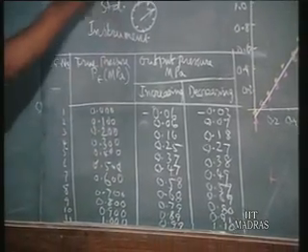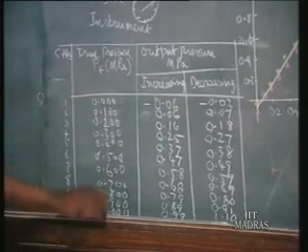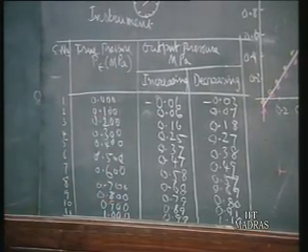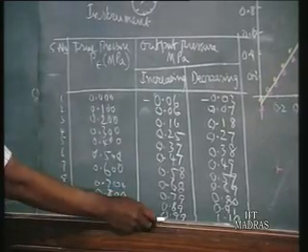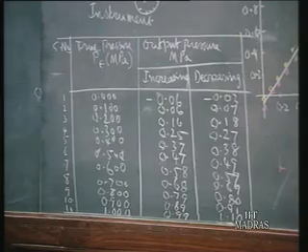Similarly we increase the pressure in steps of 0.1 megapascal and conduct this experiment until the standard instrument reads 1 megapascal. So at that time the instrument under test shows 0.99. This is what is shown.